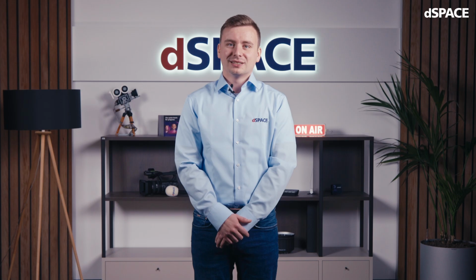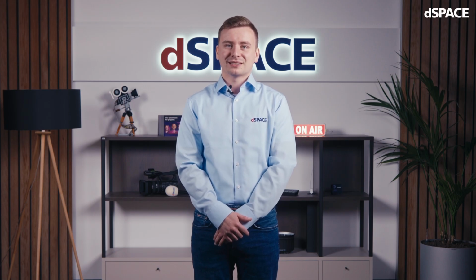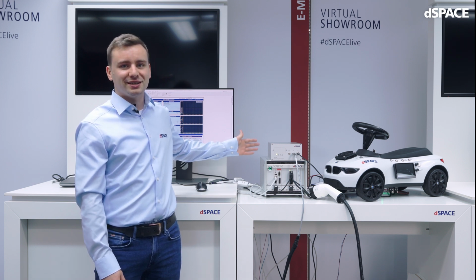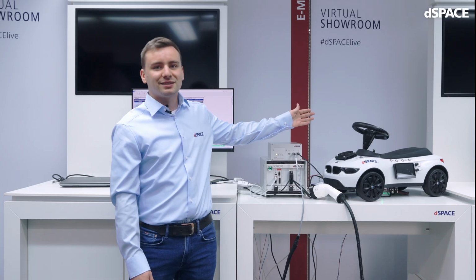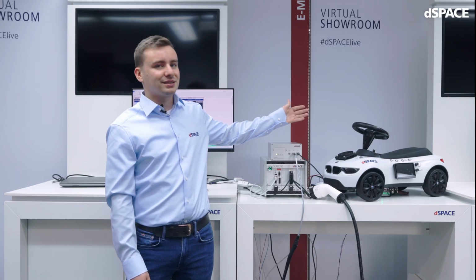And now I'm going to show you a demonstration on how to validate and test the battery data exchange protocol. This is our test setup here. We see on the left side the smart charging solution by dSPACE, which simulates a charging station and can be used to validate and test electric vehicle charging controllers or even electric vehicles in a HIL environment. And here on the right side we see our Bobby car, which is a simulated electric vehicle which implements the battery data exchange protocol. And we will then see how the packets are sent by the electric vehicle.